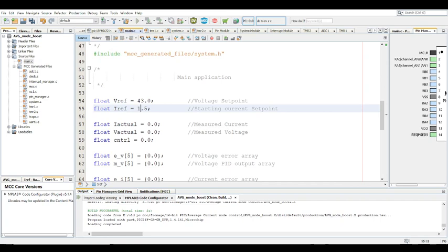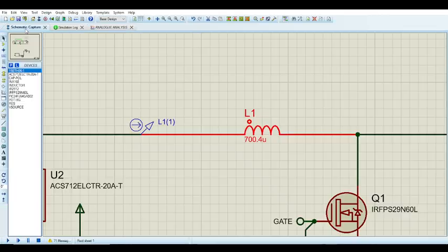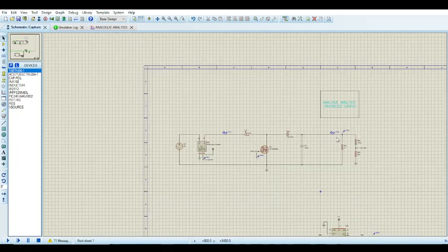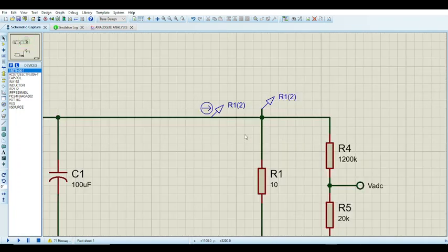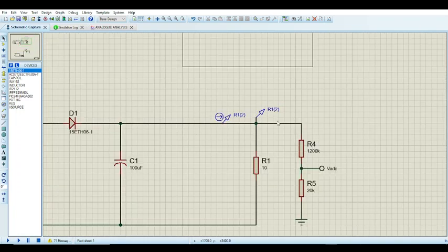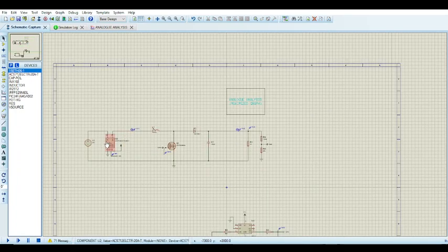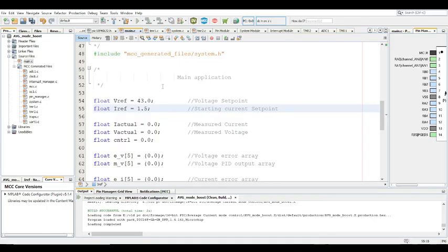And if your requirements for your boost converters are really low voltages, then I don't really think you need CCM, to be honest. You could just do it with one voltage loop, or just one output current loop. And obviously you change the positioning of your current controller to be here, not where it's at now, but there you go.